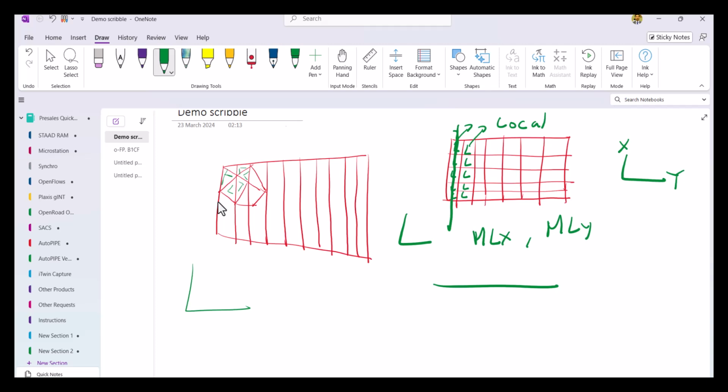The moment calculated for this, if I see this is x and this is also x, would be about this. The moment calculated for this, if I consider this as x, would be along this. So all would have a different axis of bending against which the local axis moment is considered, because all the moments are calculated about the local axis system, and all the local axis orientations are very different from each other.